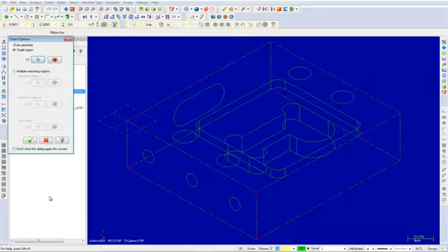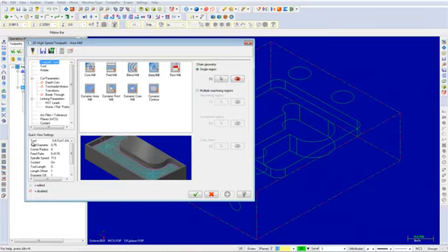The Chain Options dialog box will appear. Again, select the OK button. In the Toolpath Type page, select Area Mill. We will now choose the 3/4 inch flat end mill from the library and set the tool parameters. To do this, select Tool from the Tree View list.